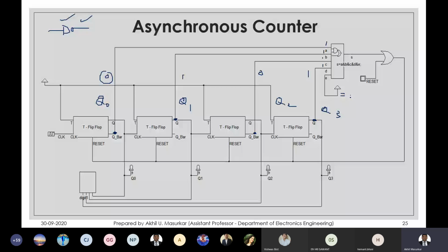So this is like a 4 input AND gate, 1, 2, 3, 4, and the inputs here are going to be Q0 bar, Q1, Q2 bar, Q3, and here we will get the output. So this is the slight hardware that you have to design. If you are drawing it in your notebook, then you can show this gate directly with four inputs.